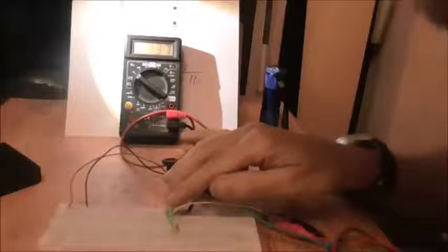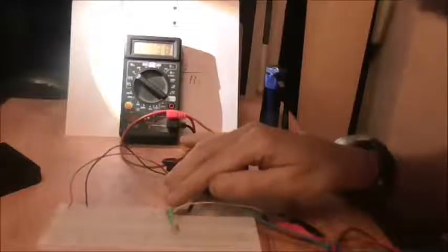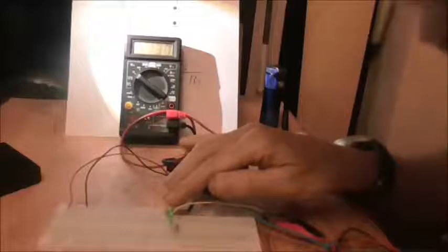What happens if I shield it from the light and make it darker? Well, this time the voltage goes down and the LED goes out. And what we've made there is a light activated sensor. So merely by swapping around which way the components go and making one R1 and one R2 or vice versa, we can make the circuit activate on light or activate on dark conditions.